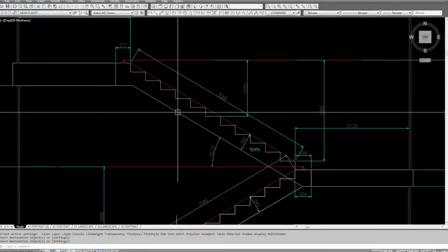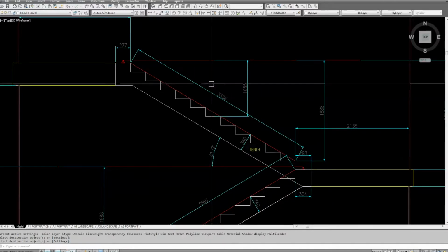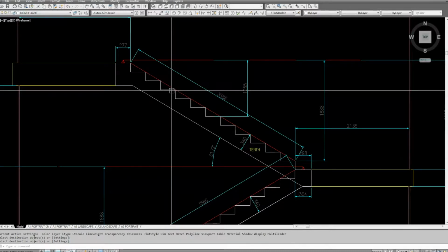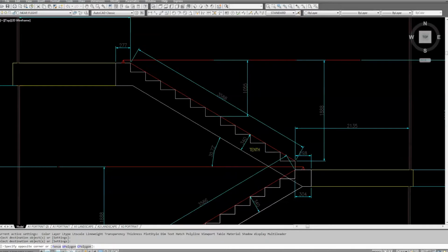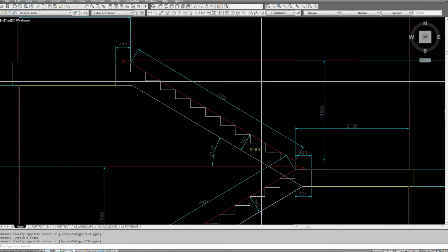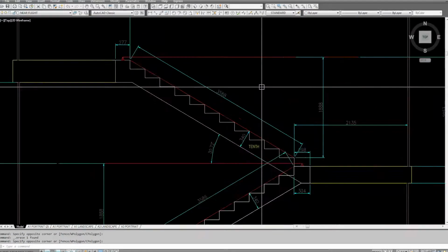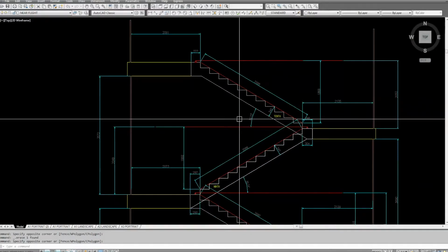So you need to predetermine which treads you're going to be fixing posts to, and then measure down to each one individually, even if that means you've got 2 or 3 additional dimensions on your surveys, which is just damn sketching, to be fair, onto those generic survey sheets. But most stairs that I do are side fixed anyway, so it works perfectly for that situation.